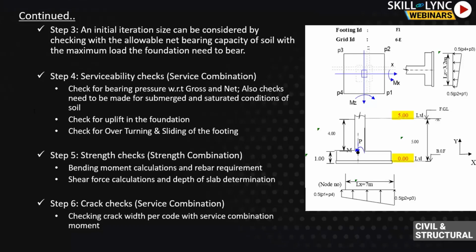Once you've made all your load calculations and combinations, you would have 3 different types of loads. One is vertically downward, which is called the P force over here by the slice side, and the other 2 different forces would be shear forces along the plane of the footing slab and the moments that are generated at the base of the raft.